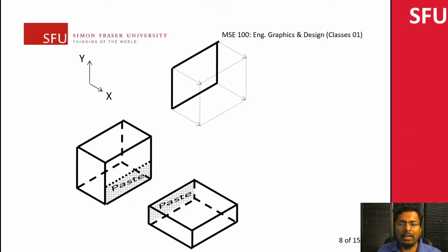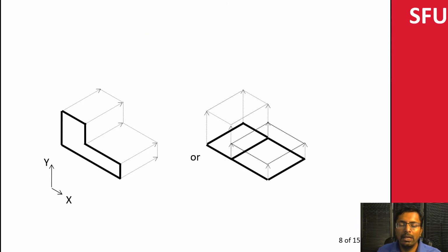So we look at a couple of other ways. You can extrude the same shape. For the L shape, the easiest way would be to look at an actual L shape and then extrude it. If you're looking at the XY shape, you can extrude it along the Z direction. The other way to do it would be to create two different rectangles on a single plane and then extrude it up. So let's quickly look at those two ways of doing the extrusion.